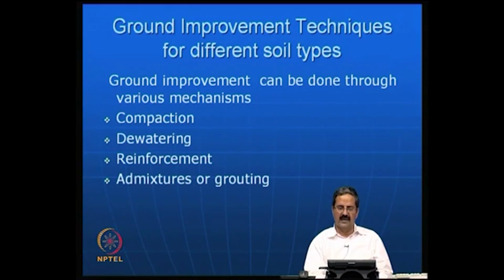So, what we do is reinforcement in the form of steel strips and geogrids, which we will see, they can influence the soil similar to RCC, reinforced concrete. We use what is called reinforced earth or reinforced soil. We use the reinforced soil technique in a very big way and improve the soil behavior. In fact, whatever you see in the case of flyovers which have metallic strips or geogrids is only because of this.